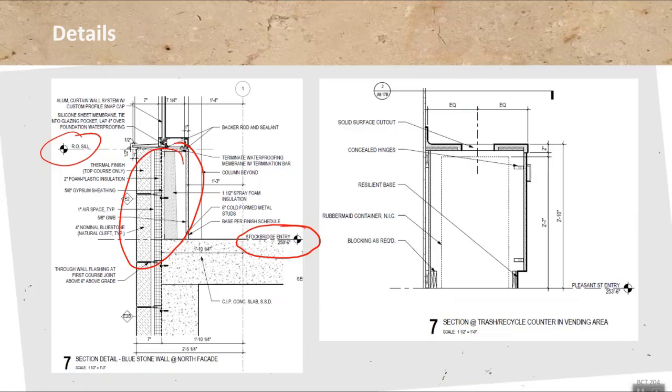So then you'll see all of that, and you of course also have a bunch of dimensions. Depending on what's needed here, there should be enough dimensions presented for you to understand what goes where. And typically you reference something that's fairly common, and you build inside to out. So you'll see here my column grid is shown, and I'm dimensioning the wall to the column grid, which allows you to build out the details, because typically the structural column will be up first, and then you'll fill in walls much later.